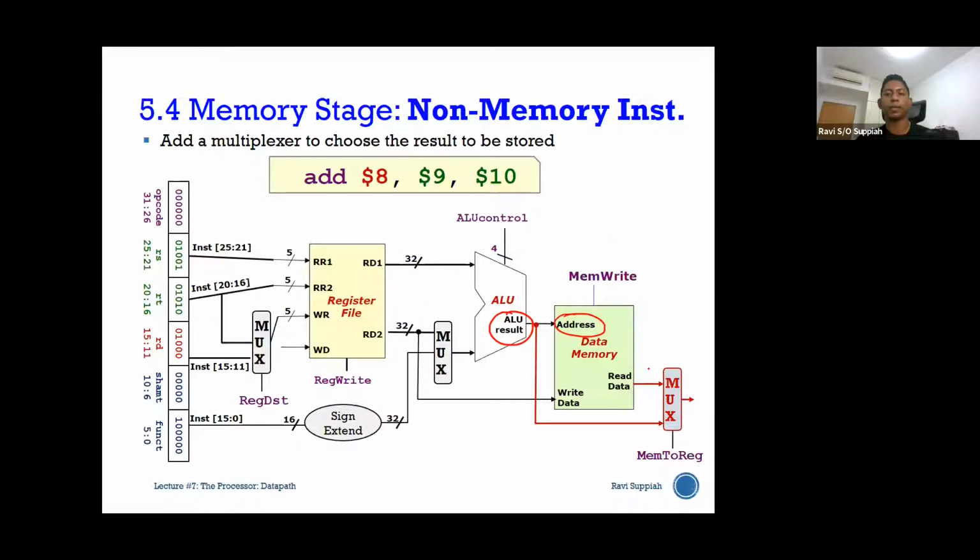All right, but it doesn't mean that I'm going to be updating the memory all the time, because again, it links back with the control signals, whether I'm doing a mem write or mem read. If mem write or mem read is not activated, then even though the address bus has some information, I'm not going to change anything or access any part of the memory.